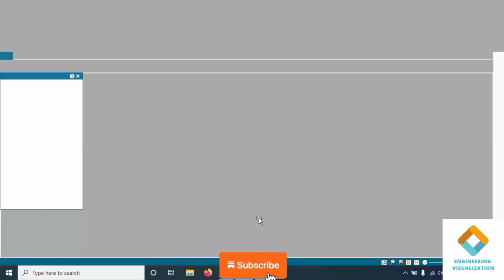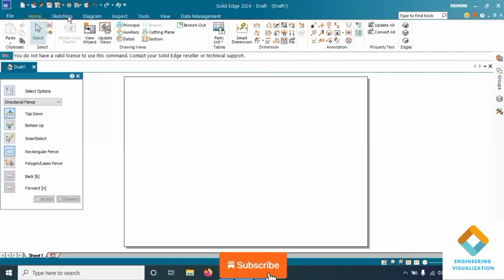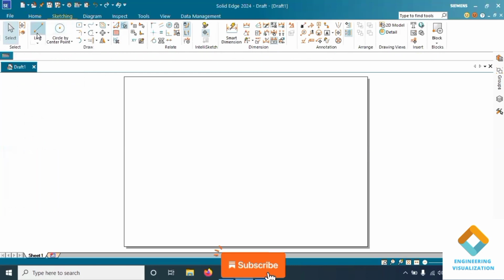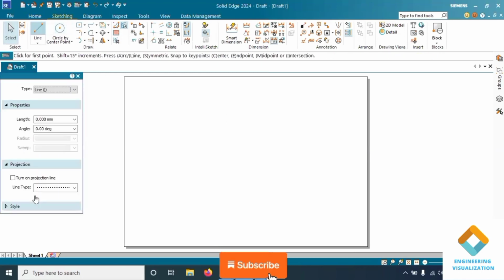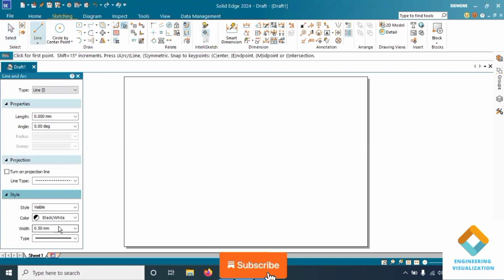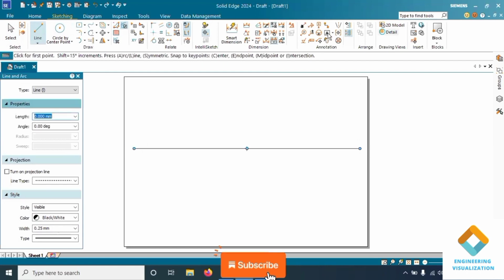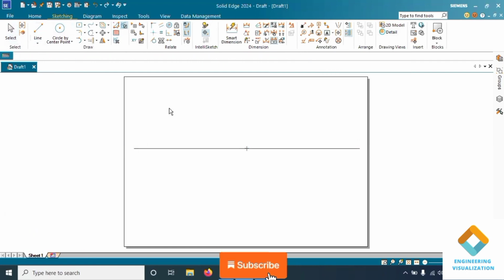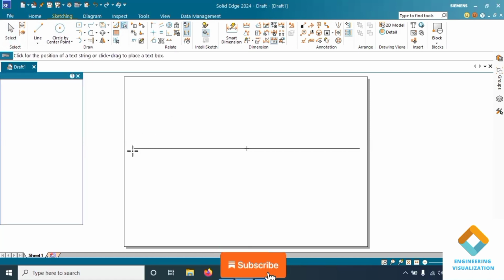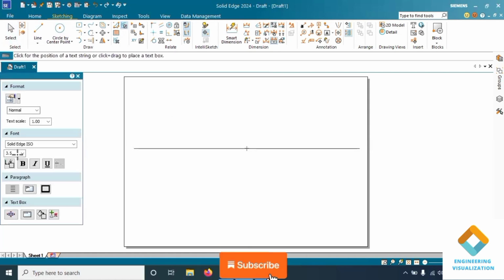So in this problem we have to use the dimensions of the ellipse, that is major and minor axis. The circle dimensions they have not given, and it occurs in the front view. That is, we need to use the major axis of the ellipse, 60 mm, in order to construct the circle. This is one of the special type of problem. So in this problem they have not given any kind of inclination. We have to use the data which is given in the problem to solve the problem.